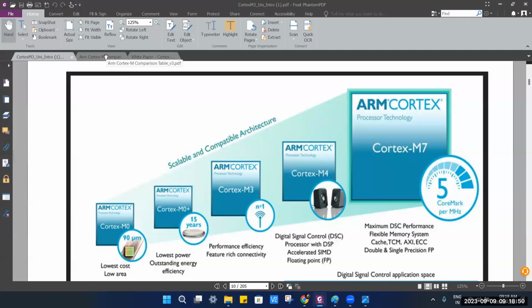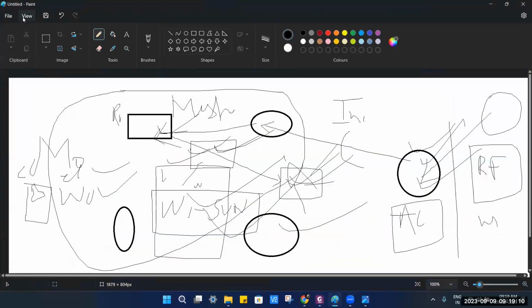See, there is something called MMU and MPU. MMU is the memory management unit, which is used in a full-fledged system. It is present in Cortex A, and MPU is present in a Cortex M system, which is a very restricted version and will not handle certain high-level virtual memory management. So that is one fundamental difference. Another difference is that an MCU contains all the things inside, like RAM and ROM. It's an SoC, a system on chip. So that is the main difference.